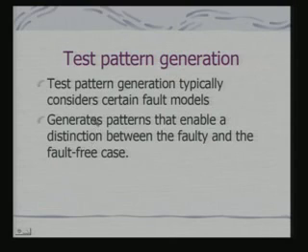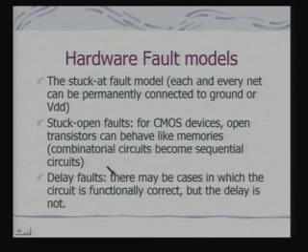Test pattern generation typically considers certain fault models, because without the fault models you cannot really generate the test patterns. So, what does that mean? It generates patterns that enable a distinction between a faulty and a fault free case. So, what are different kinds of fault models? Typically, we are looking at hardware fault models.